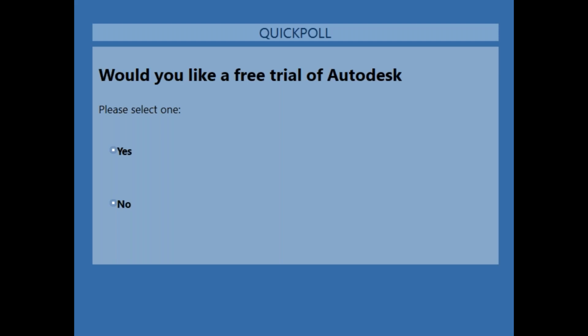Another question I'm seeing here is where is the 3D image generated from? If you're talking about that 3D model that I walked through for the 3D takeoff, that is taken directly from a Revit model. All you have to do is upload that Revit model directly into Autodesk Takeoff, and then you can start that takeoff process there.